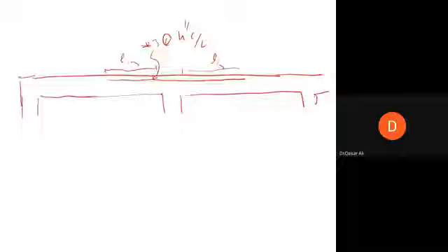So it has nothing to do with the spacing at any other location of the negative reinforcement, because the reinforcement will be curtailed and it will be placed as stop bars. So this reinforcement spacing has nothing to do with this reinforcement spacing or this reinforcement spacing. Okay, but in the positive reinforcement, apart from the convenience in the placement of reinforcement for a fabricator, there are practical issues. For example, let's say we want to place reinforcement like this.